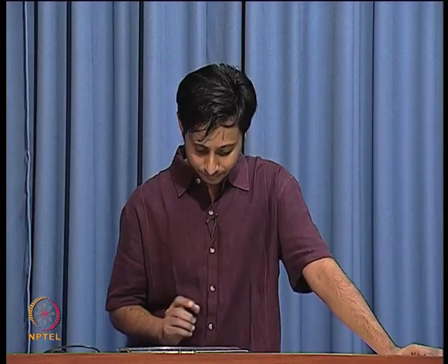What it does, every system unless it is a passive lossless system, every other system adds noise. If it burns power, it adds noise. So, a low noise amplifier is most probably going to burn power, in which case it is going to add noise. Now, what we are going to try to do is to make an amplifier that adds as little noise as possible on top of the signal. So, this is the low noise amplifier. This is the first block in the chain.